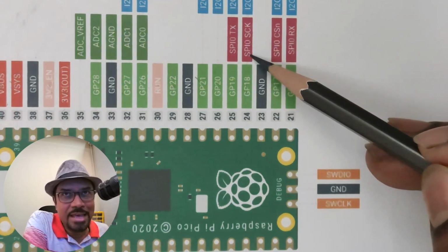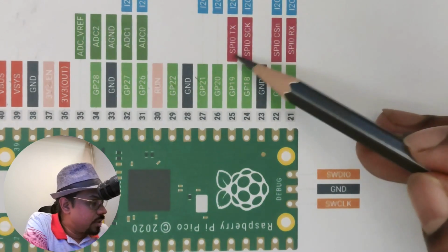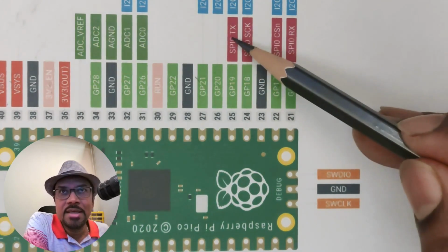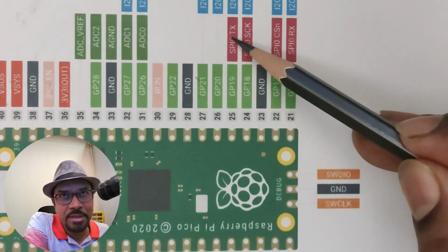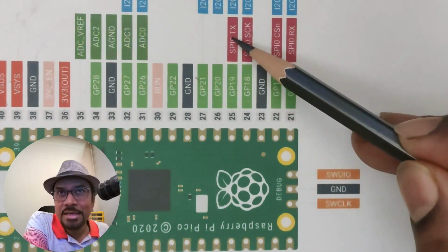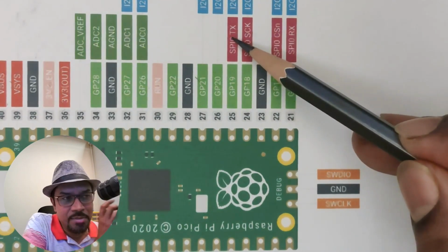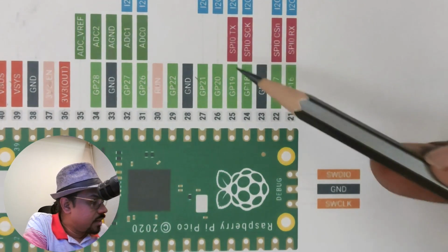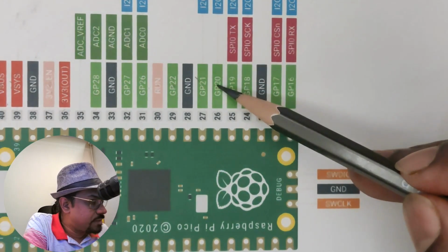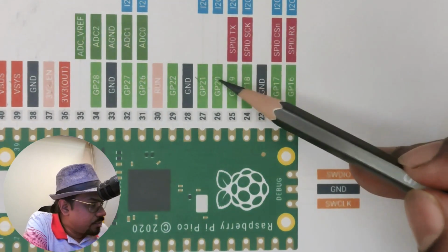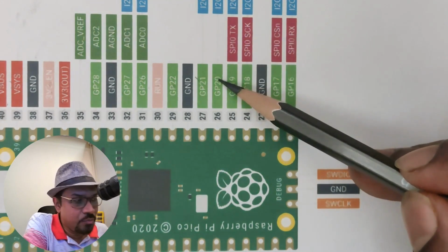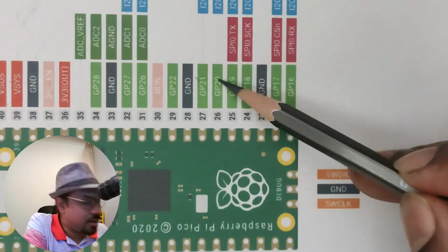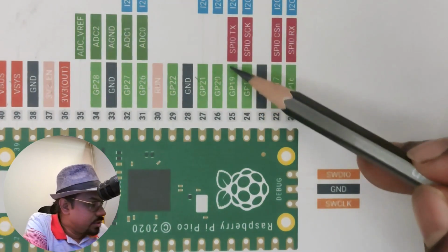The CLK or SCK, whatever you find on the board. And this one, the SPI TX, will be connected to the data pin or the DIN or SDA pin. So if you either see a label called SDA or DIN, this is where it goes to, right? I'm also using GP20, which is a general purpose pin. I'm using that for DC. I'm connecting it for data command, right? So data or command selection. So these are the pin configurations that you can see here.